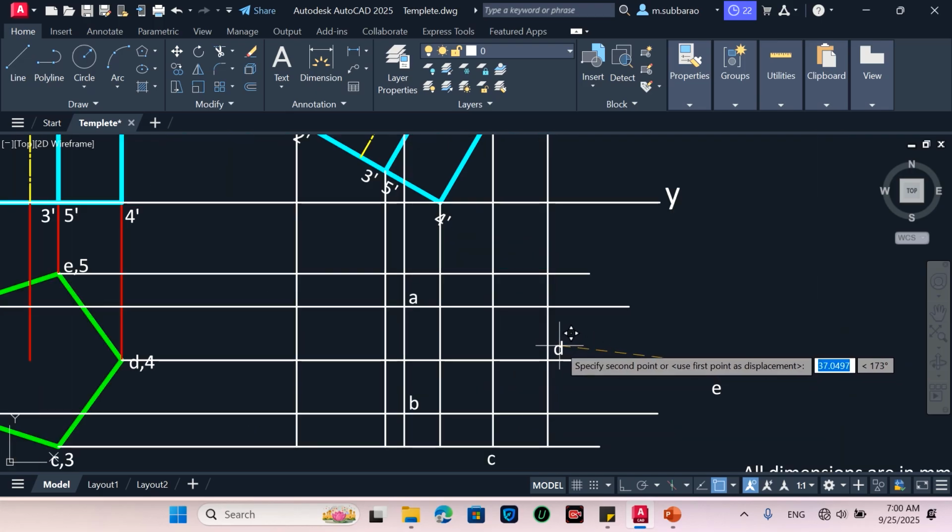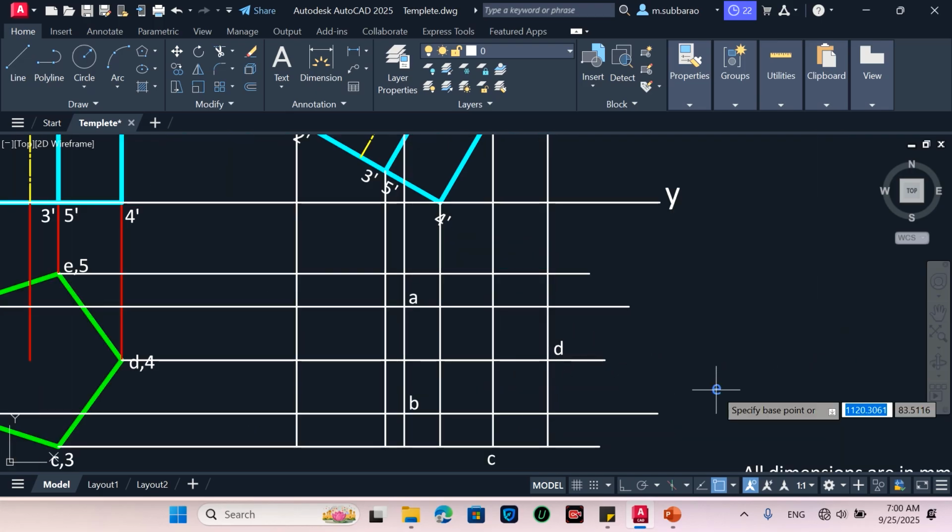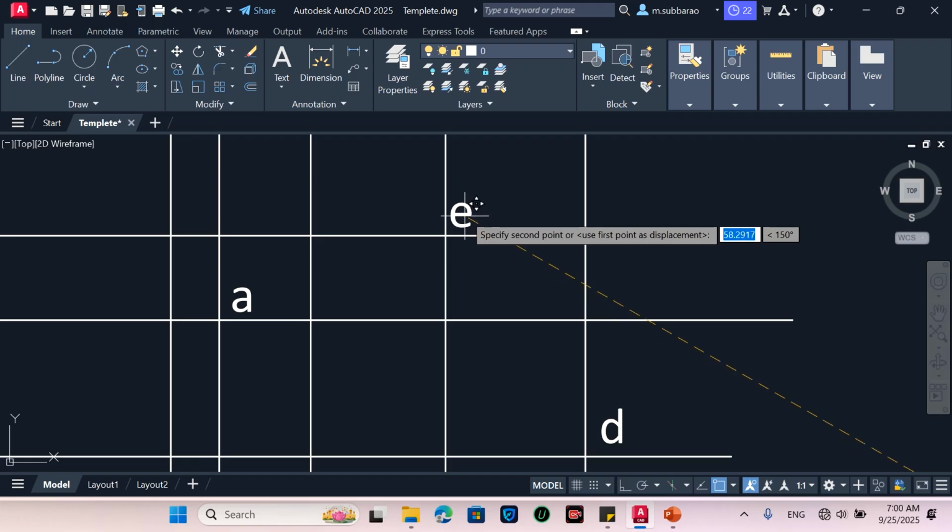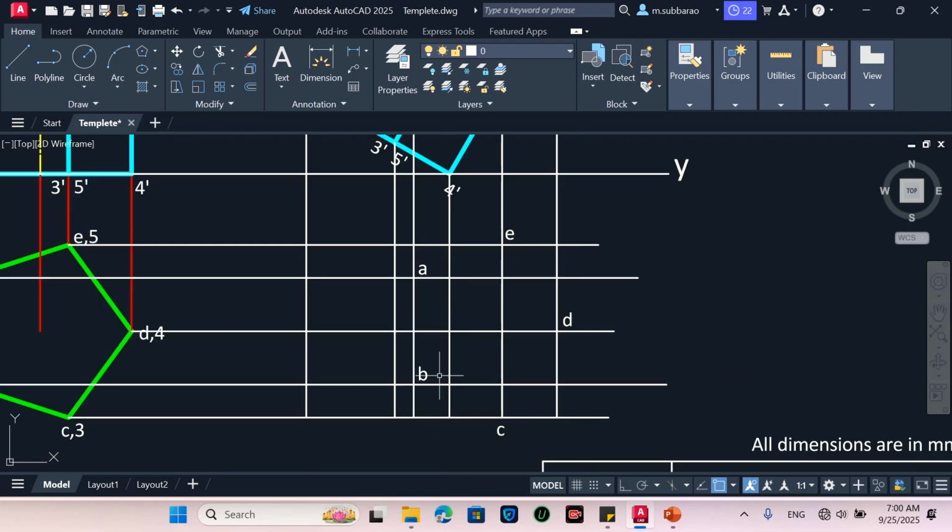These two are matching here, are coinciding here, and this becomes the E. So this is the top base. A, B, C, D, E is the top base. So now you try to draw the top base with the line. So draw a line from A to B, B to C, C to D, D to E, and E to A. So now remaining all things are projection lines.